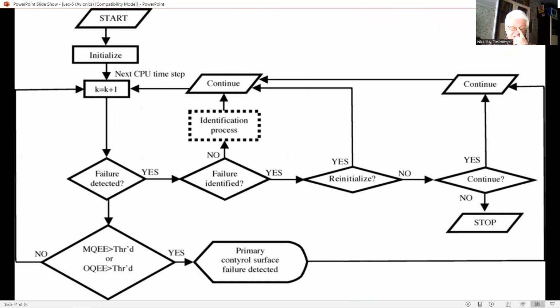The variations between the filters used to filter sensor output noise are also minimized by using accurate, stable components in the filter. The failure detection algorithm enables the detection and isolation of a sensor whose output departs by more than a specified amount from the normal error spread.